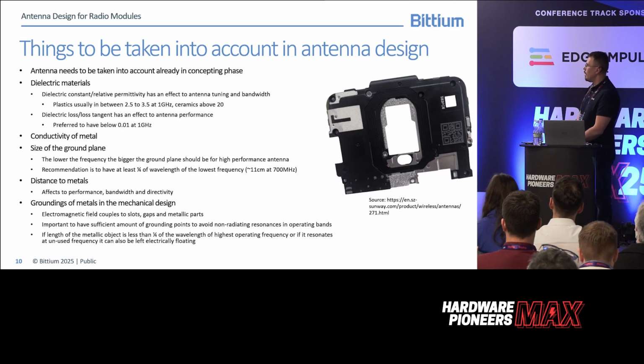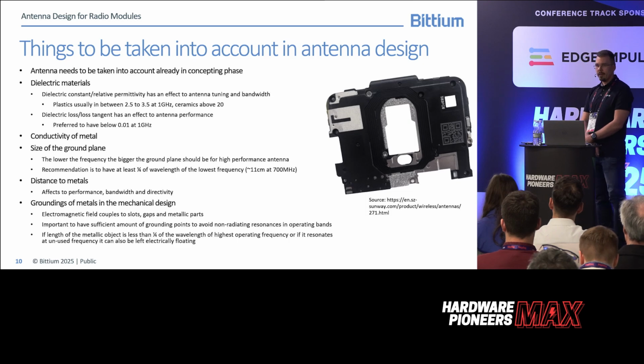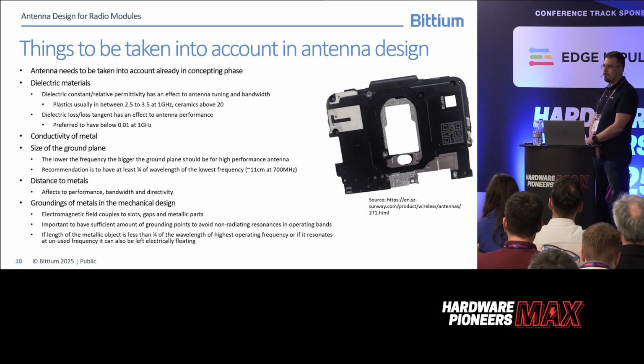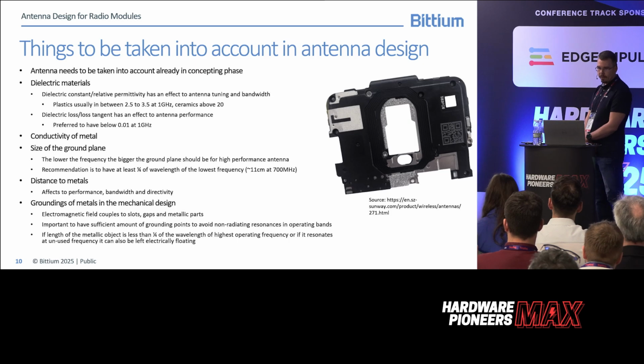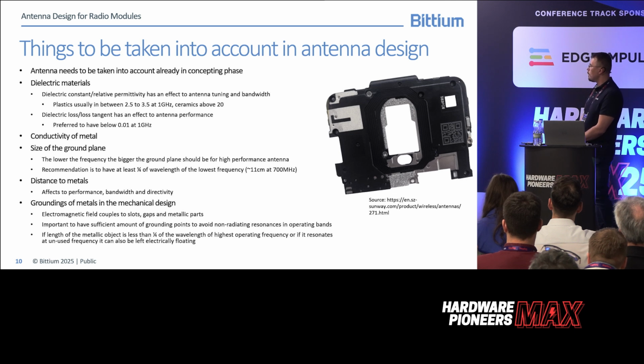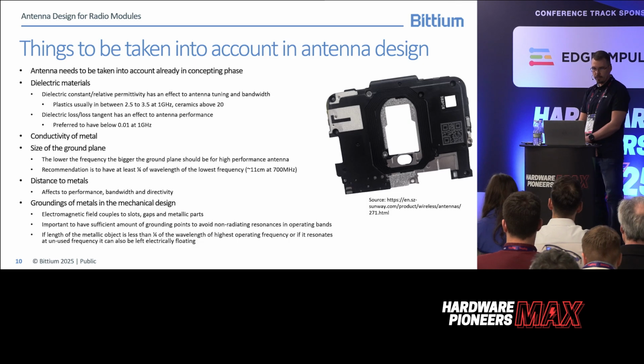Many times customers come to us and they have already built the first prototype and they are having connectivity issues, and then they have not reserved enough space for the antenna, or the dielectric materials around the antenna are selected so that the antenna is not tuned correctly, or the dielectric material is causing too much loss to the performance.